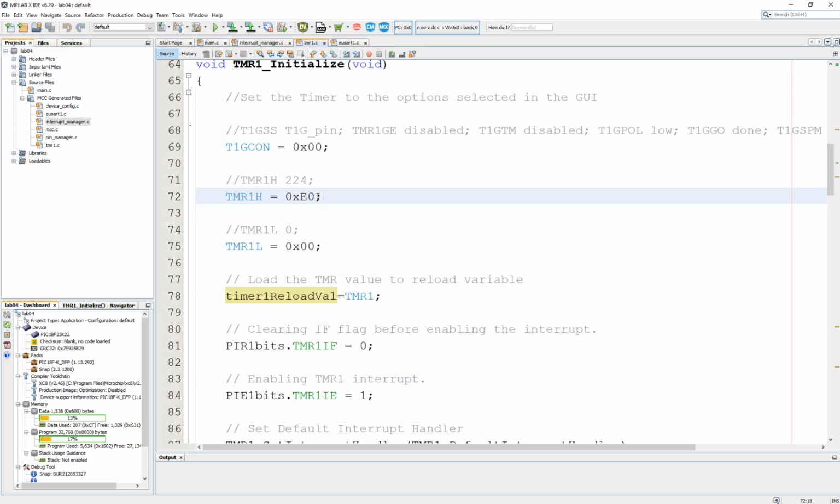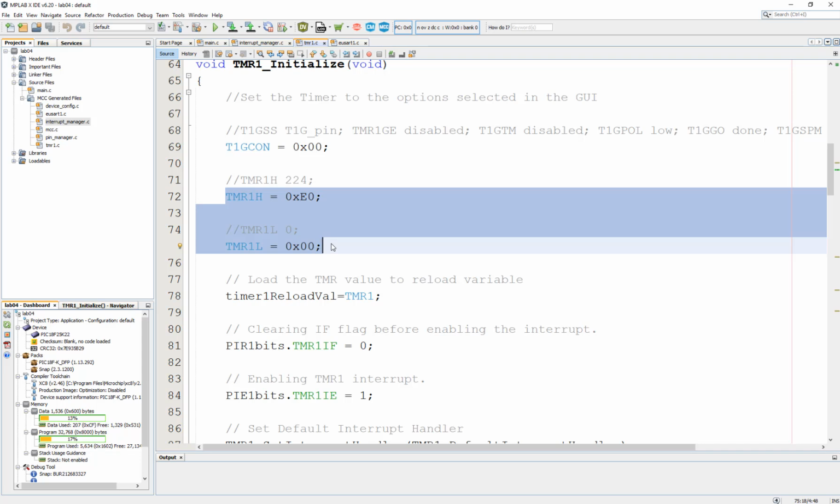You couldn't even identify it when you are listening to the speaker. I think put a 0, 0 is fine. This one will give you a starting value for timer 1 to interrupt at the very first cycle. You don't really have to worry about it. Can you really figure out 4.1 milliseconds versus 5 milliseconds for the very beginning? You turn it on, you are trying to count. Nobody can tell that. You turn it on, it just does whatever it does. So the initial values don't really matter because they're being overwritten by your interrupt routine.